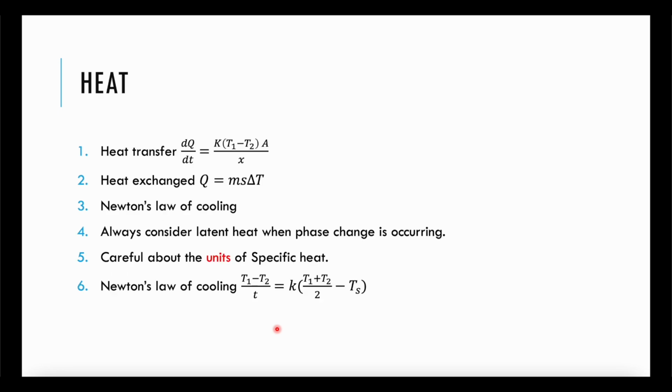Alright, so heat is also important, and the most used equation is the heat transfer equation, that is, the rate of change of heat that is going out of the system or coming to the system is equal to the thermal conductivity times the temperature difference times area divided by the thickness x. Okay,